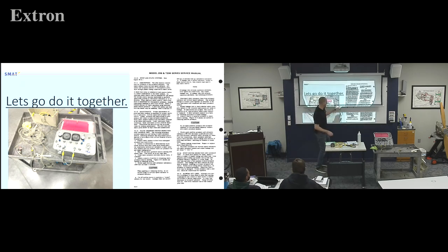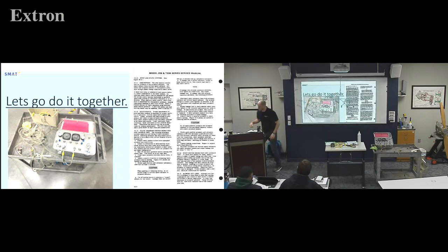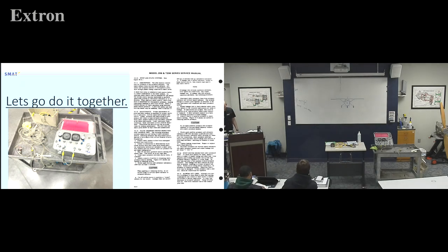So let's run a fake one on this fine aircraft Parker drew us. Now one test, and probably the first one I'm going to do, is my pitot system test. I'm going to hook my pitot checker up to the pitot tube. So say he's stuck on there, we're going to roll this up. We're going to watch the airspeed indicator. Let me double check my book, how fast